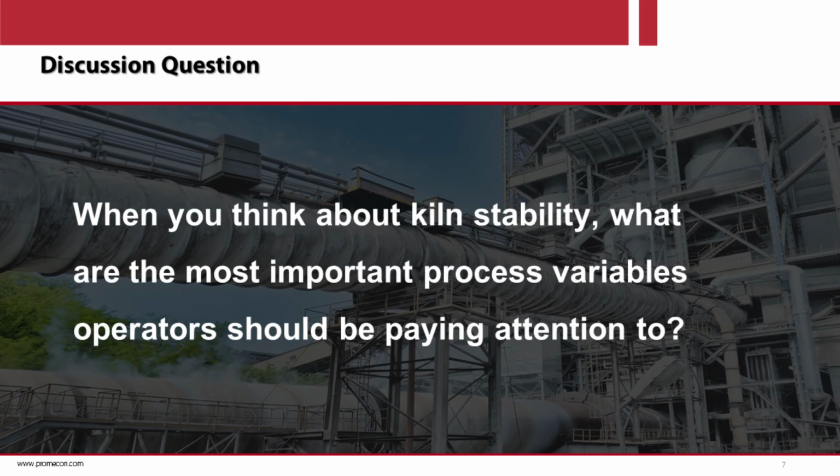a very important variable for the operator to know, but also the cyclone temperature to see if there is a good heat balance through the preheater and through the cyclones, and the calciner temperature. So that will reflect the heat balance and also the combustion stability in the entire system. So if you have a healthy preheater, you have more chance to have also a healthy kiln. It's not a guarantee, but a good start, let's say.